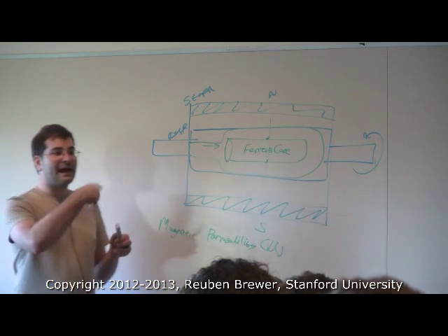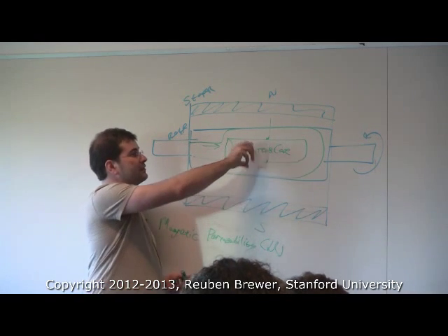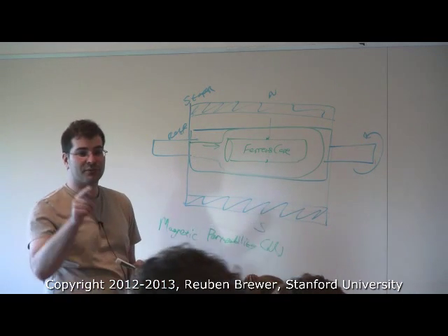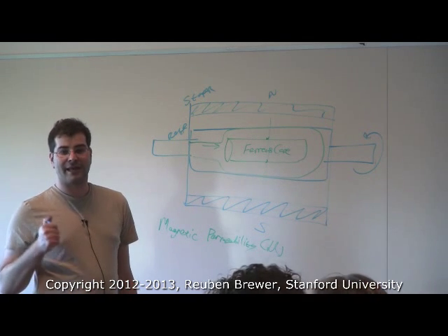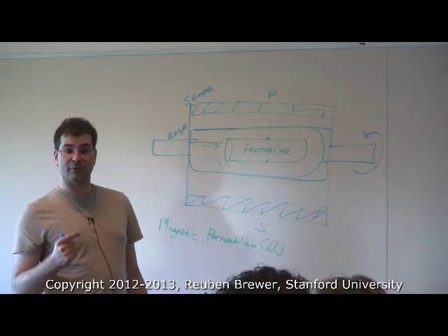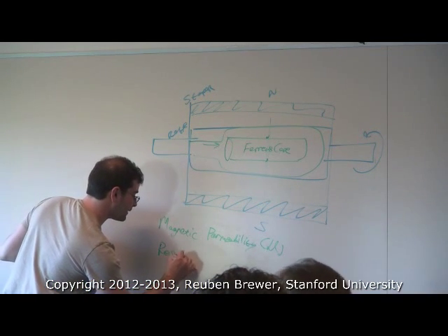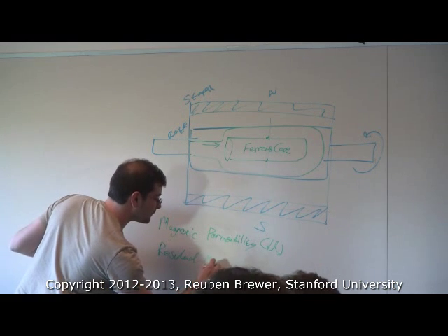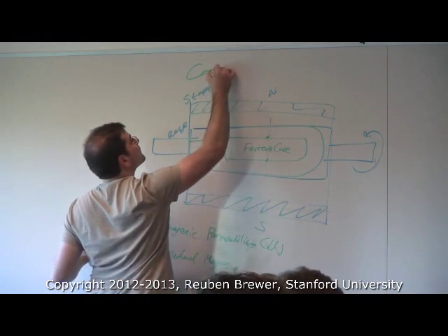So then as we get in different positions, with the power off, the two magnets want to interact. So that's what you're feeling. You're feeling a cheap motor that has a ferrous core that has been magnetized a little bit, with just a little bit of a residual magnetic field. And that's what's causing the cogging.